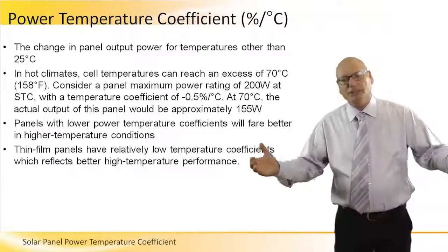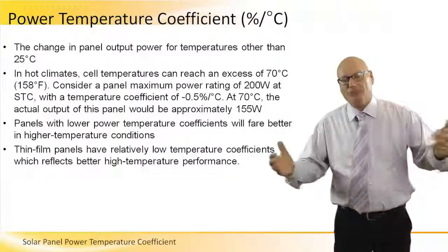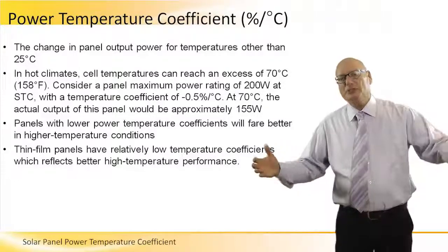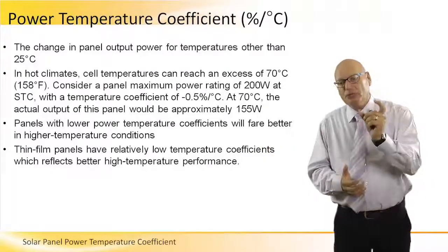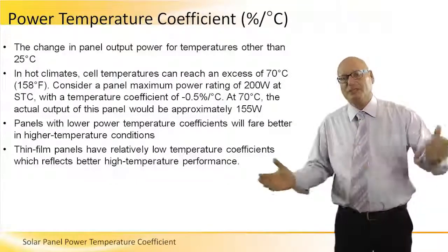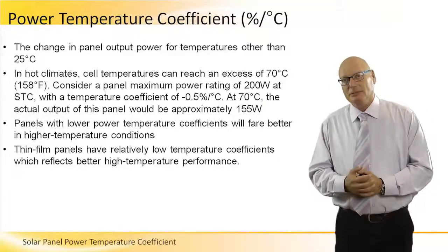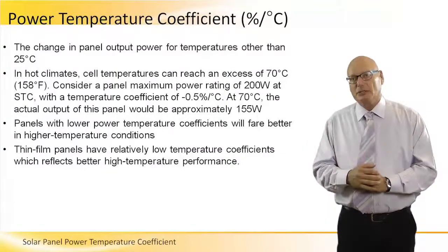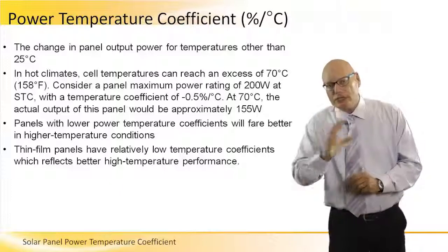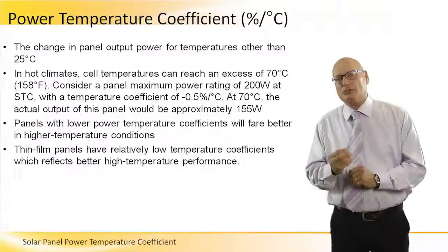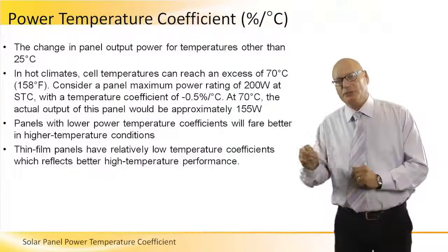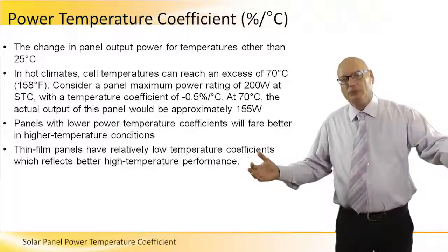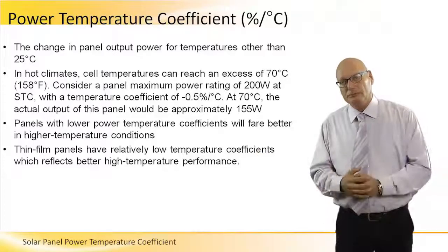And if we have a 100 kilowatts system or 1 megawatt system with, let's say, 100,000 panels, each of them losing 45 watts, that's a tremendous loss. So I'm not interested in this slide talking about percentages. I'm trying for you to appreciate the loss of watts, the loss of power because of the temperature coefficient. Especially when we come to build a large farm.